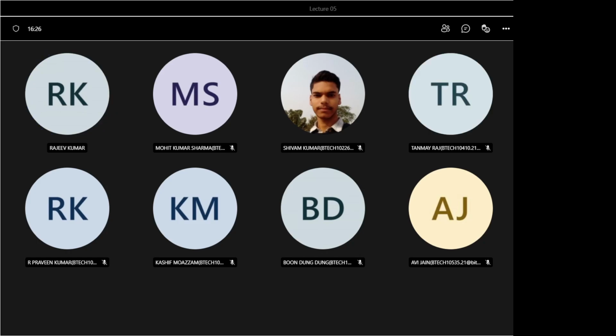Acts vertically normal to the support on which the roller rests. Reaction force generated from a roller support has only one component and acts vertically normal to the support on which the roller rests. This also I will utilize in the truss system. That truss is resting, one point is fixed and the other point is supported on the roller. So there you have to imagine only one reaction force will act.